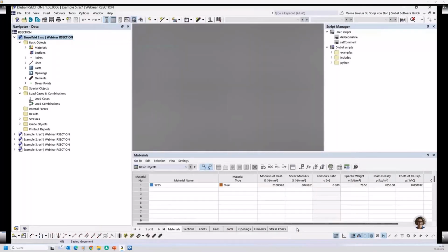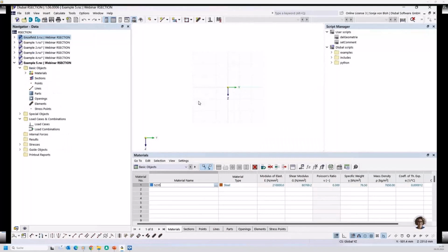You can model the openings by using elements with a 0 thickness, since the cross-section has a hole only at this considered member location, and the complete cross-section before or after ensures the connection in the member. The cross-section is connected, and it's also possible to transfer the shear. Therefore, I have to define an effective thickness for shear transfer. I will do this now. I want to create a channel section with a hole in its web.